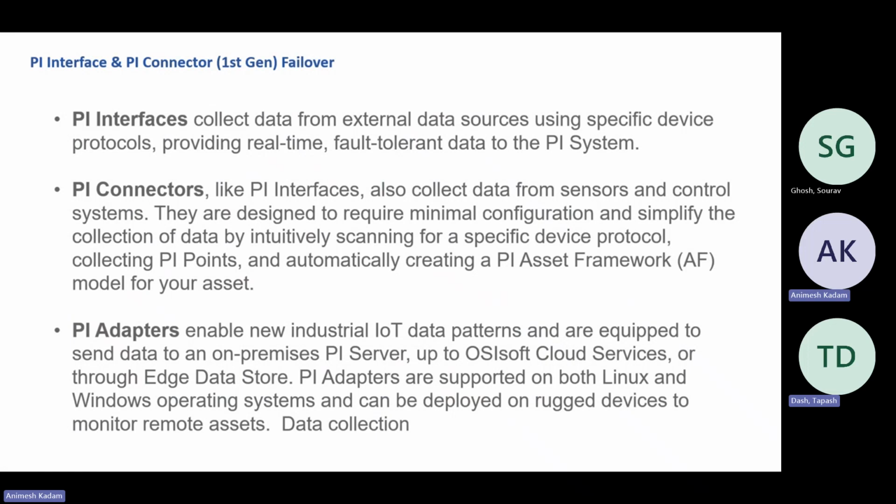Not necessarily, a PI connector may not be available for your PLC. So PI connector is available for certain types of specific systems only. PI connectors are not available for every type of data source. It is specifically designed for certain types of data sources.